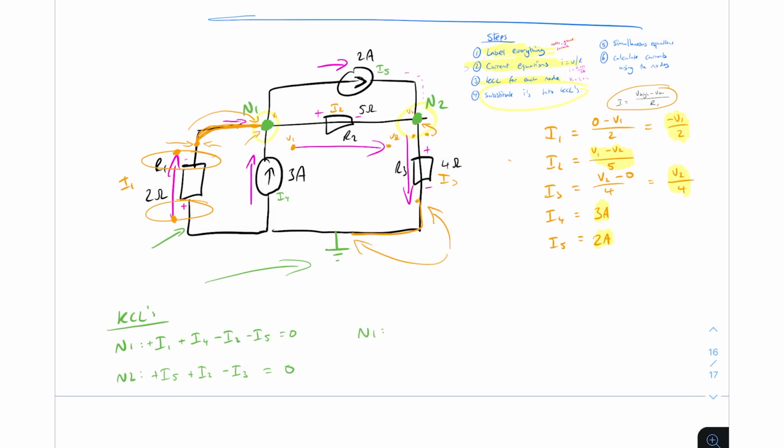So node 1 is equal to I1, which we've said is minus V1 divided by 2. So we put minus V1 divided by 2. And then we've got plus I4, which we know is 3 amps. So plus 3. And then we've got minus I2, and we know that that is V1 minus V2 divided by 5. So V1 minus V2, all of that divided by 5. And then we've got minus I5, which you know is 2. Right? And then we've got node 2. So obviously we can simplify that a bit, but that's what we're going to do before we do our...